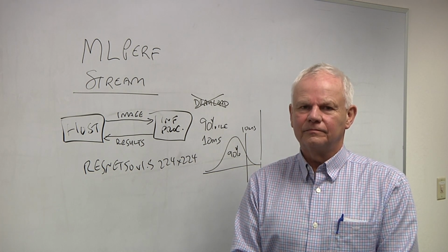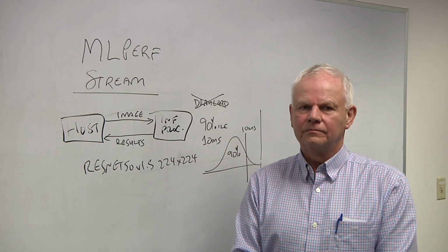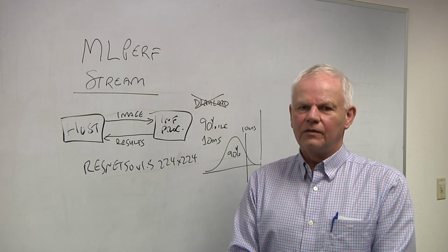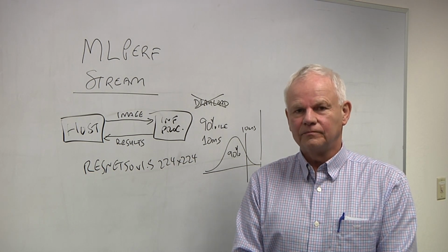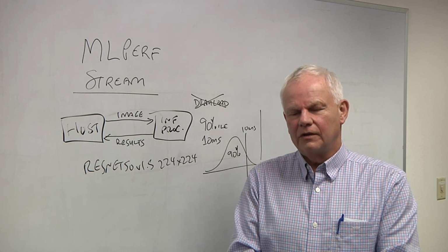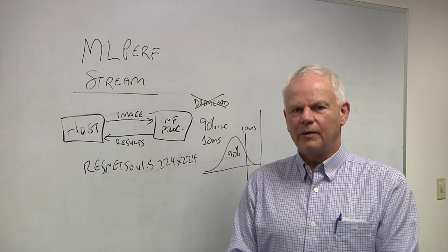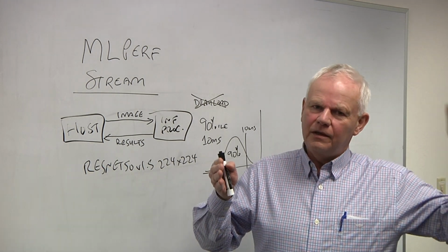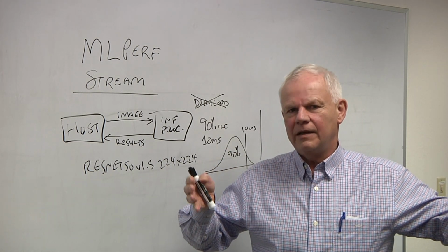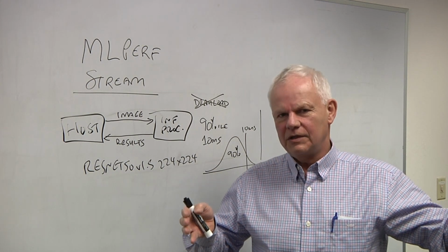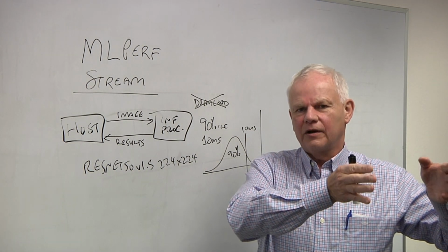But your latency is now a function of where is that chip in relation to something else too, right? Yeah, at a system level, latency isn't just the inference chip latency, it's a total latency. So if you're in a self-driving car, there will be a spec, and that spec will be from the input to the camera to the time that you start taking any action about what you're seeing. That's going to be a certain number of milliseconds, and the inference is part of it.